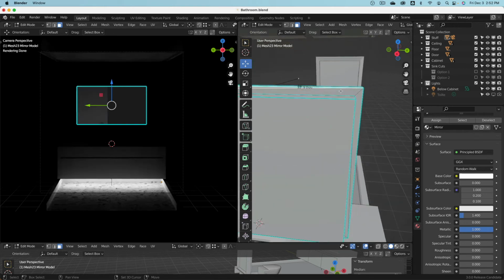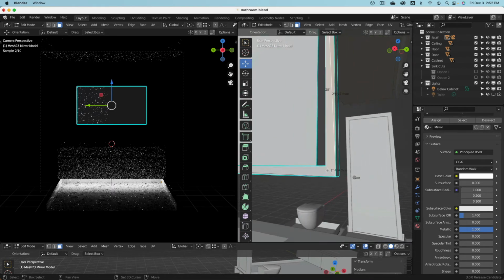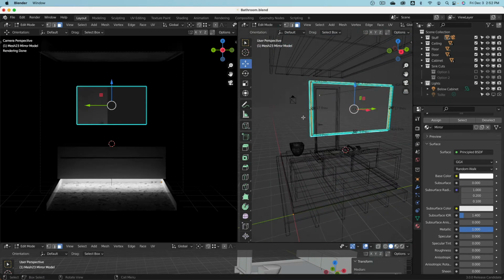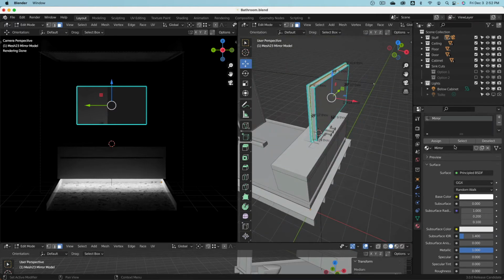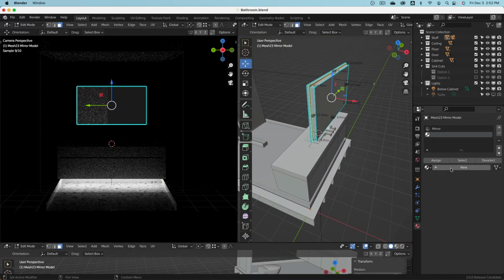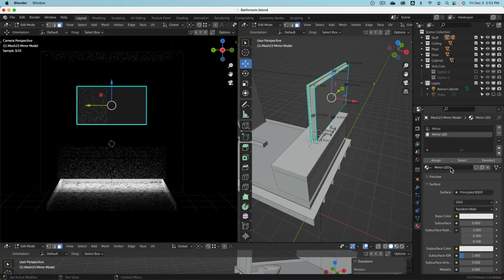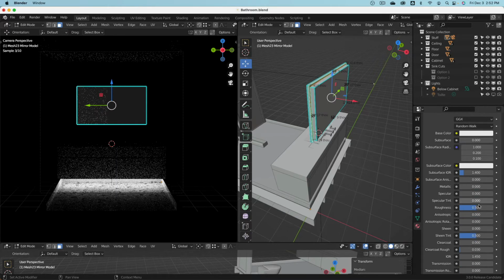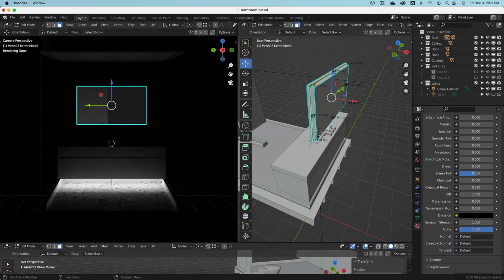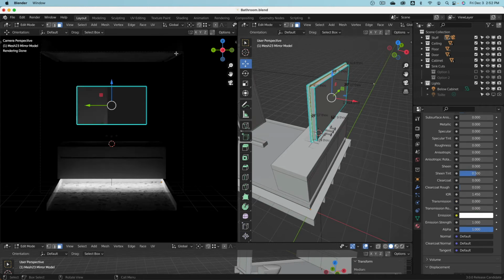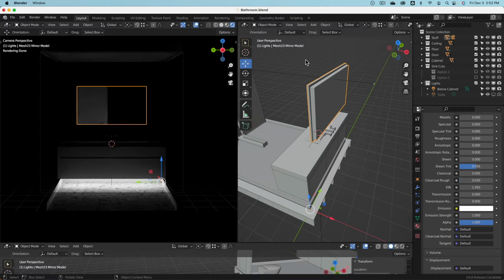So here I select all these triangles, SketchUp export it, and there, and shift click there, Z and wireframe. Yeah, this is all selected, very good. And I will create a new material, new, assign, and then I call this mirror LED. Off, off, and here's now the trick. Emission white. Don't really see much because the walls are hidden. So Tab to leave edit mode.